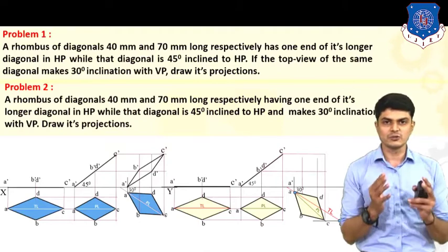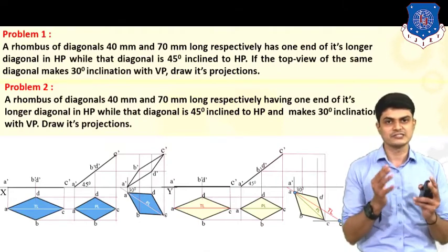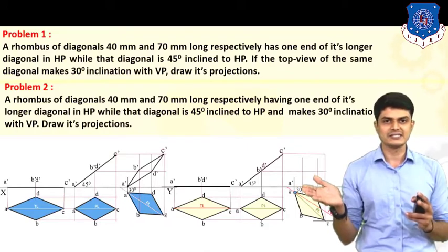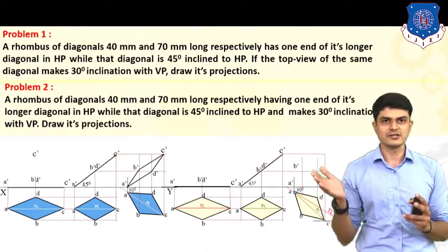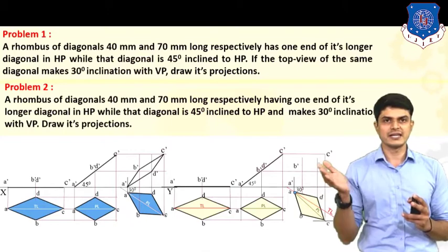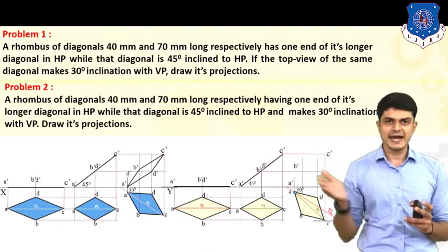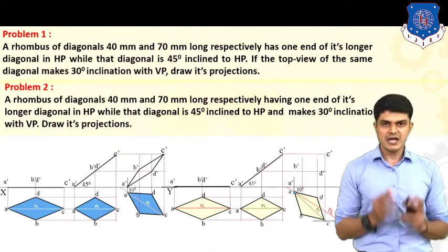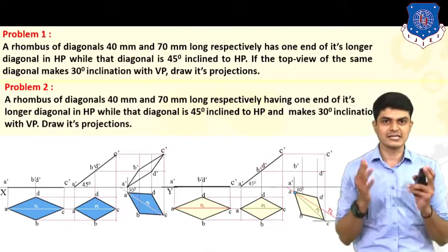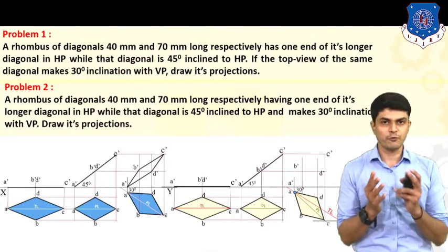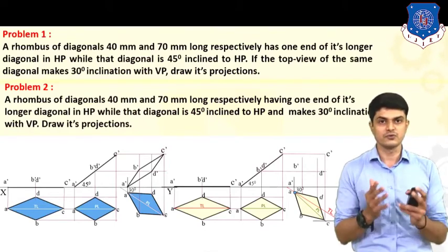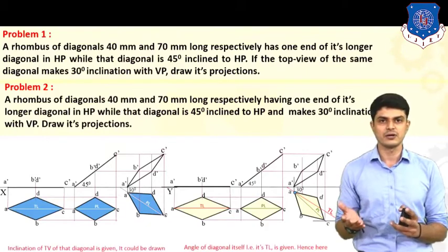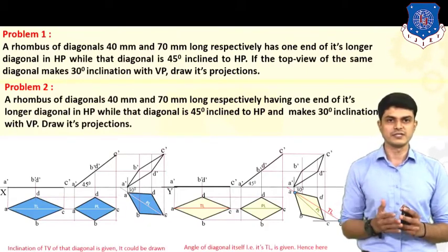Then find out the points of intersection A dash, B dash, C dash and D dash. So A's vertical line and A's horizontal line give A dash, B's vertical line and B's horizontal line give B dash, C's vertical line and C's horizontal line give C dash, and D's vertical line and D's horizontal line will give you point D dash. After having these points of intersection, simply connect these points in alphabetical order in order to finish your diagram. So let us connect these lines in alphabetical order. So this is nothing but your final object.